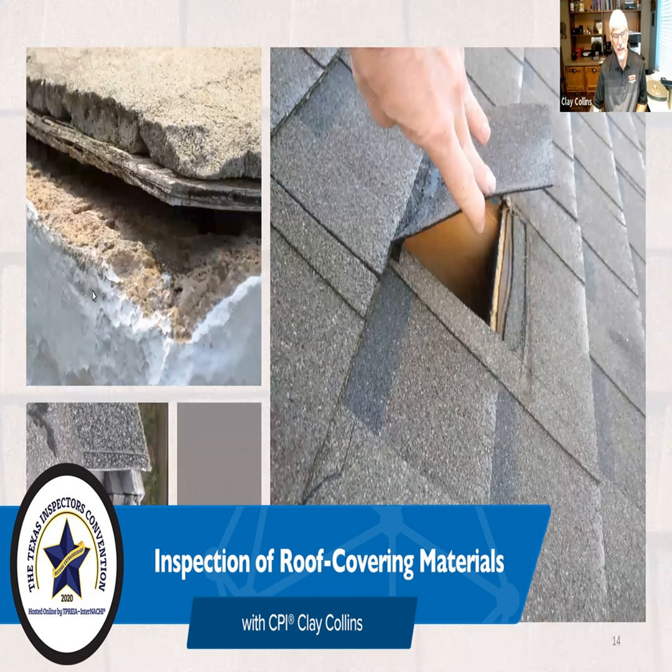Okay. What else? Last question that I have here. As soffit and fascia are above the plate line, do you consider this area roof structure in your report? Say that again, please. As soffit and fascia are above the plate line, do you consider this area roof structure in your report? In my report is the important part of that. In my report, I put it under wall cladding.